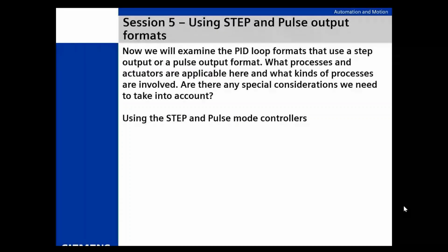Okay. The other thing, which we're going to hit on very, very briefly, is when I talk about control, I'm talking modulated control, analog. Most of the time, it's a 4 to 20. My control loop is opening and closing a valve or something like that for a level, for a temperature, for a flow, for a pressure set point that I'm going after. There are other things in the real world. There's step and pulse things. There are things that, for reasons I don't always understand, it's like a bakery. You go to a commercial bakery and they're baking loaves of bread on a giant conveyor.